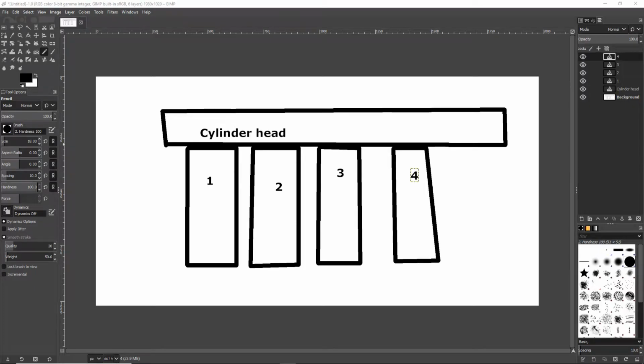He's holding it down. Alright, I want to take a minute to talk about displacement. So let's pretend this terrible drawing that I did here is the engine from the side. This is a 4-cylinder, 1, 2, 3, 4. I've got our cylinders up and down, slapped a cylinder head across the top to show you. And at the bottom here, let's pretend this is as far down as the piston travels, and all of this cylinder up until it meets the cylinder head. And we know this black area here would be our combustion chamber.